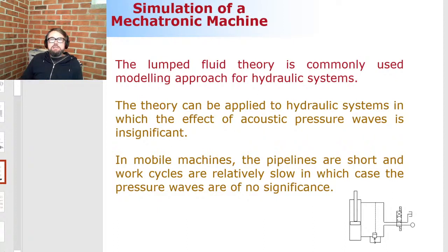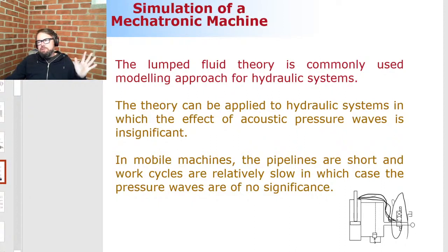It is not capable of capturing acoustic pressure waves that sometimes take place when there are really fast components. Like sometimes with a direction valve, when it is very high-end, it can open and close really rapidly. Sometimes that opening and closing can introduce pressure waves that travel back and forth in the pipeline. This is something that we cannot take into account. But other than that, it's very accurate.